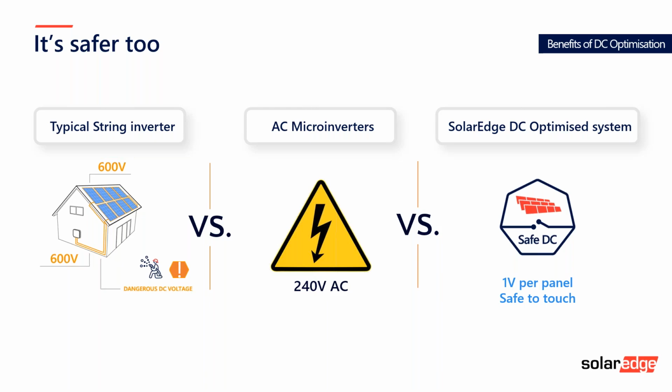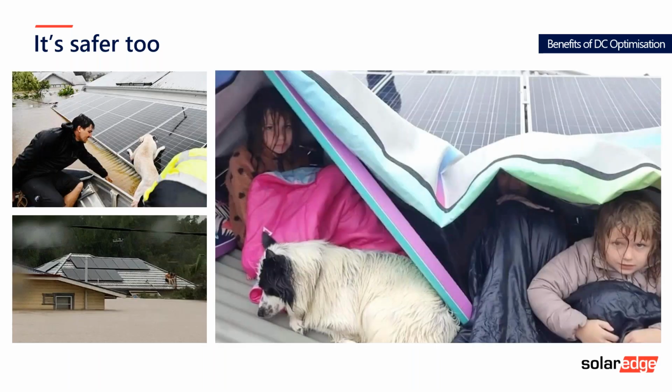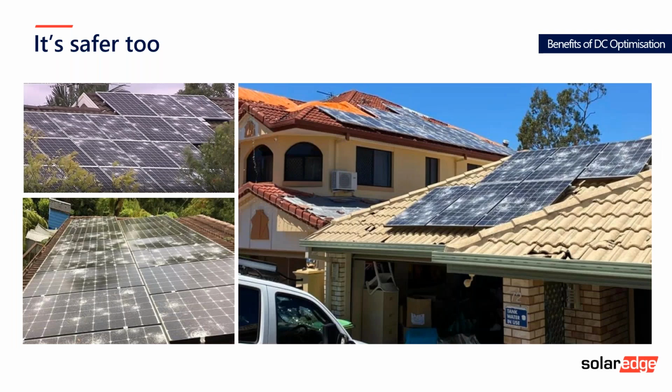And we feel that's probably the safest solution you can have, particularly when you combine that with our Sense Connect capabilities, being able to detect the temperature anomalies that lead to arc faults in MC4 connections, and there's plenty of them on the roof. And here's a couple of areas where safety is critical. A flood, so the inverter's compromised, it's underwater, but the panels are fully irradiated. And in a similar scenario, where there's significant damage from hail, bright sunny the next day, it's difficult to control those DC voltages with traditional inverter systems.